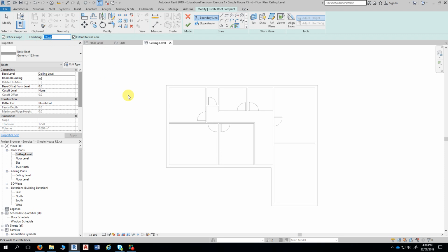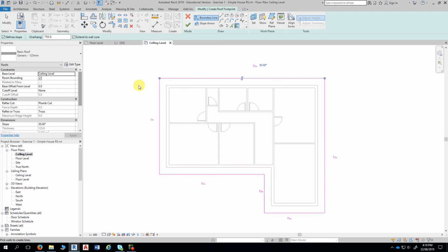So then we go and select all of our walls. What you can do is pre-select the first wall and hit the tab key. If you click into the view, pre-select the wall and hit the tab key, it will put your sketch lines all the way around, all at once. Press that, don't click. It sits in the place, but you've managed to get rid of your other one. I don't know where it is.